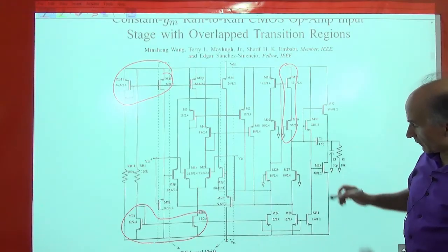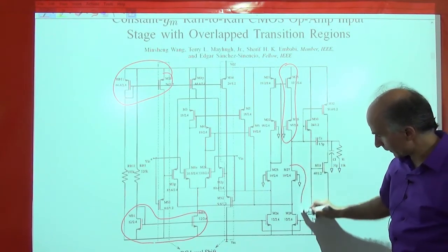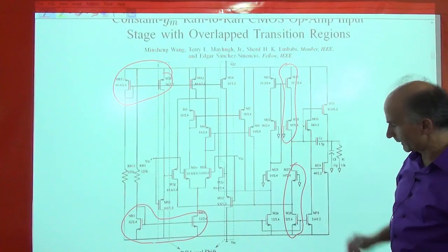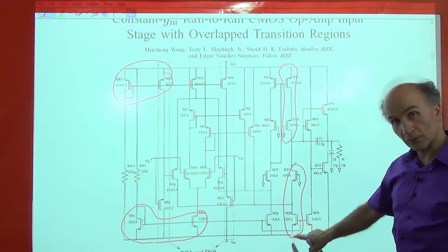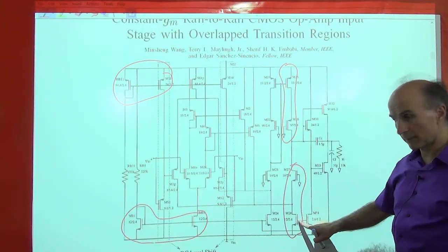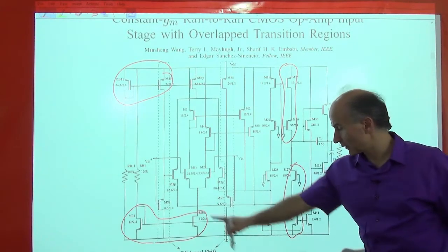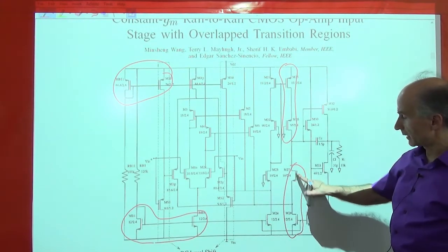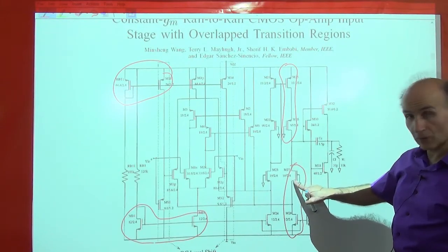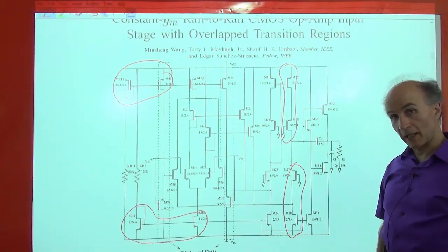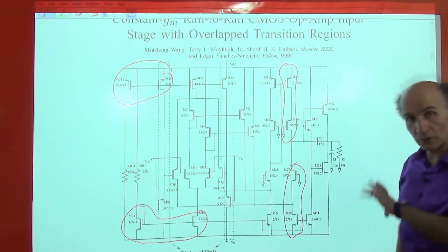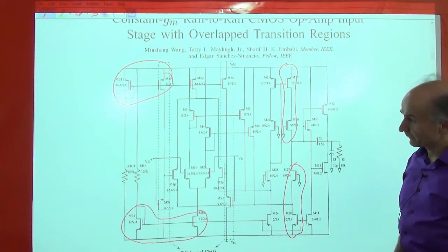All right, you can also see a cascode NMOS structure here if you look very carefully. Right, you see that we have an NMOS with the source grounded, gate going to some bias, actually coming from a current mirror. And then this is another NMOS device with its source connected to this drain. So these two form an NMOS cascode structure. Okay, so far so good. We begin to see certain things.